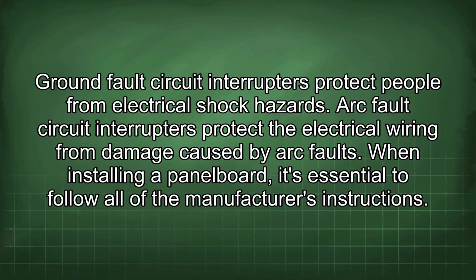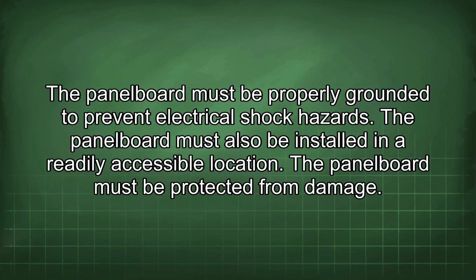When installing a panel board, it's essential to follow all of the manufacturer's instructions. The panel board must be properly grounded to prevent electrical shock hazards. The panel board must also be installed in a readily accessible location. The panel board must be protected from damage.